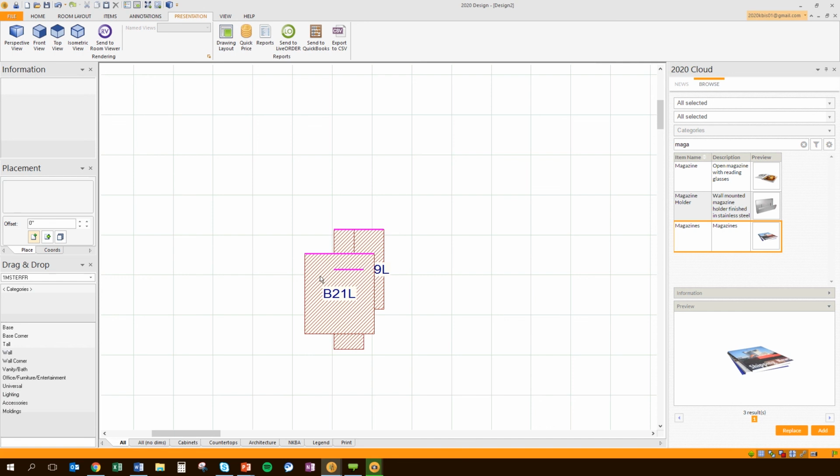So what are we doing here? If we slowly mouse over this item, you'll see in the bottom right corner your item and all the other items that it's been in collision with. So there you go. So this is very nice to be able to quickly adjust and clean out a kitchen that has a colliding item, you're not too sure with what.